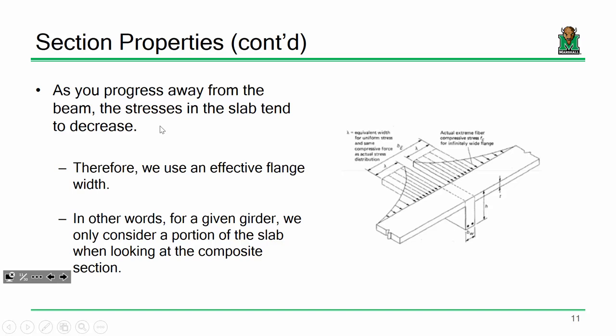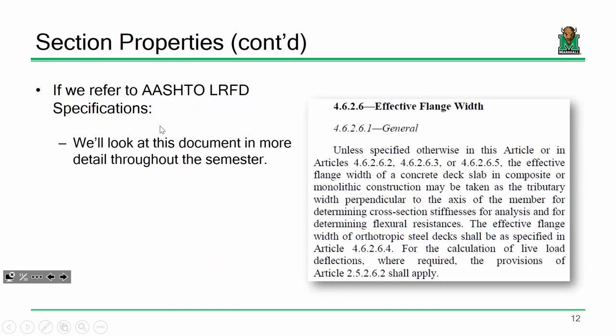You've got a floor system that has a slab and a series of rectangular beams, and when you look at that in a composite state, you cut out a slice of that slab and you've got a T-beam, right? I'm sure you all have done something similar when you took concrete design. And if you look at the American building spec for effective flange width, there's all these weird little rules, like it's the minimum of the span length over 4, or all these different categories. We kept it pretty simple in the bridge industry.